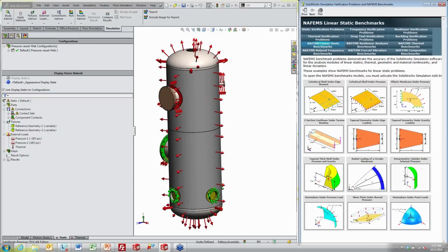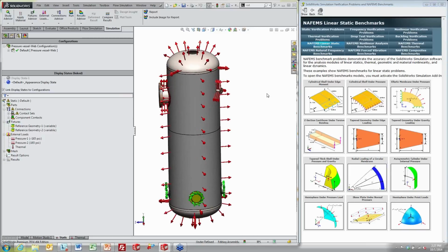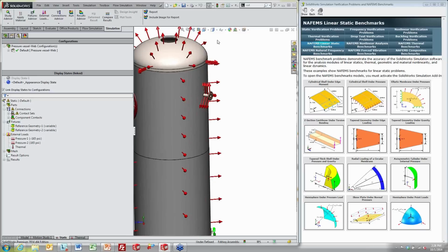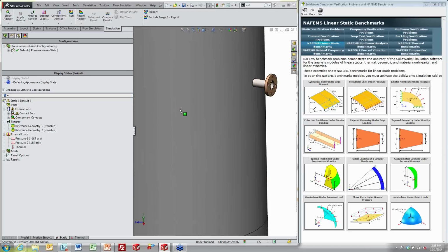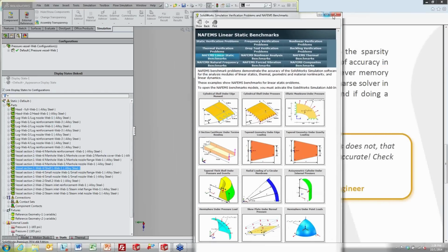Now, the one way assumes that you're using a shrink fit. I will show you here on this model so you can get a look into it. You are making an assumption that those parts will originally be modeled the way you've modeled it in SOLIDWORKS, and then you're going to push them apart forcibly. So you're going to have a big displacement stress at that corner that you're talking about, Joe. But I'll show everybody else how to ignore interferences without fixing your model. I'm going to return this back to the way it was before. Get rid of this.